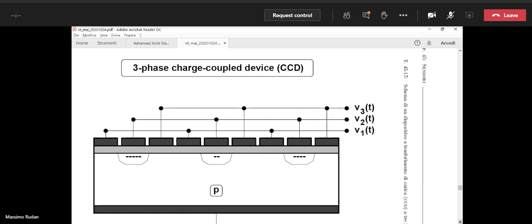So during the integration time, some charge is integrated in these 3 photocapacitors, okay? For instance, photocapacitor the one on the left, number 2, has a stronger illumination, so there are more electrons in the inverted layer, okay? Photocapacitor number 5 has not so many electrons because the light at this position in space is weaker. And photocapacitor number 8 is somewhere in between, okay?